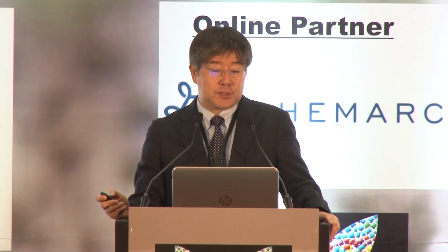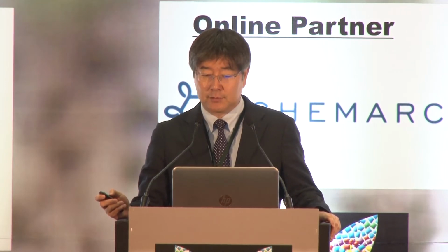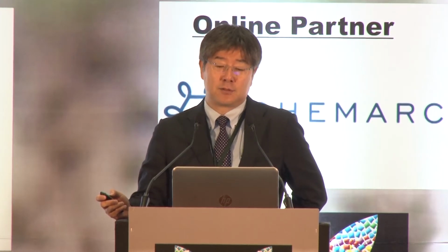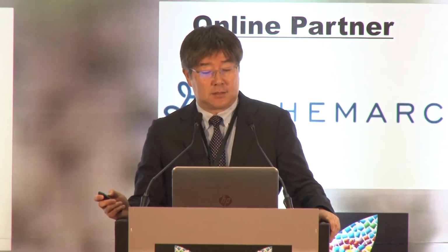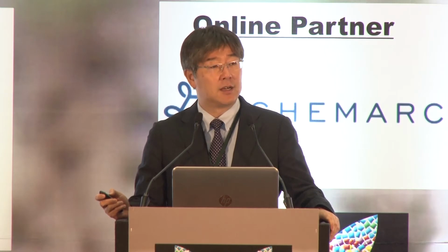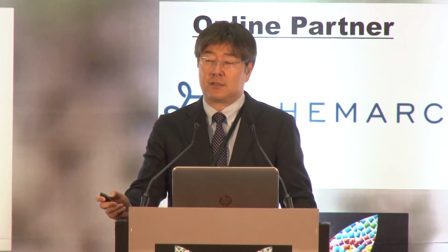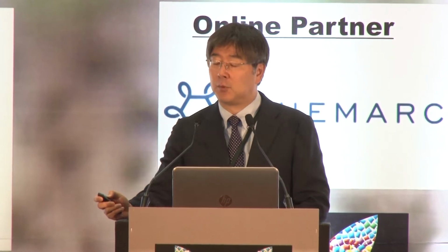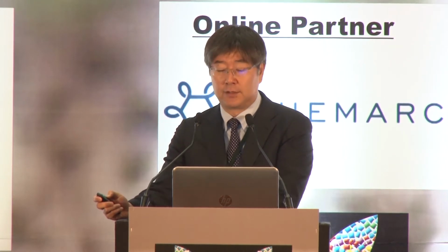So the next solution is an N-methyl type HALS system, especially for interior parts application. This is LA2, Adeka Stab LA502XP. This is an N-methyl HALS plus synergist system. The benefit of this product is superior thermal and light stabilizing activity, color sustainability, and long-term heat resistance. And this product also has superior compatibility with the polymers. Especially, this product is very suitable for interior application.